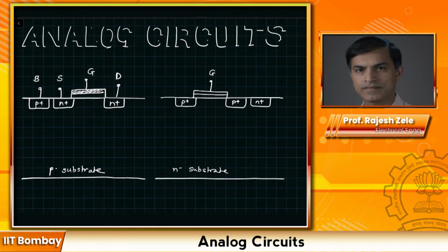However, this is not possible because if you remember, during the first lecture itself, I showed you a single wafer. That single wafer is what you start off with, something like a P minus substrate, and on that you develop all these different transistors, right? So for developing a PMOS transistor, you cannot have yet another substrate. So what you do then is you create an island for the PMOS transistor as follows. I am intentionally showing you this so that you understand the concept. So we will be starting off with the same. We create an island using well diffusion